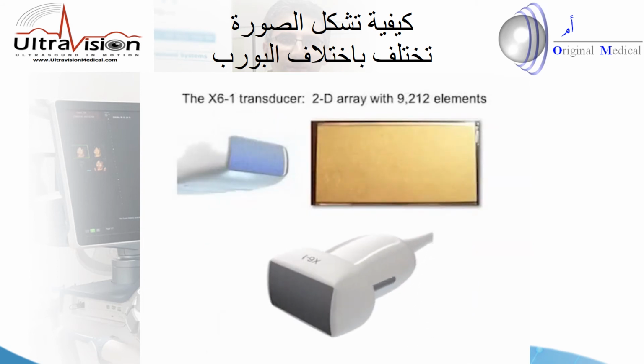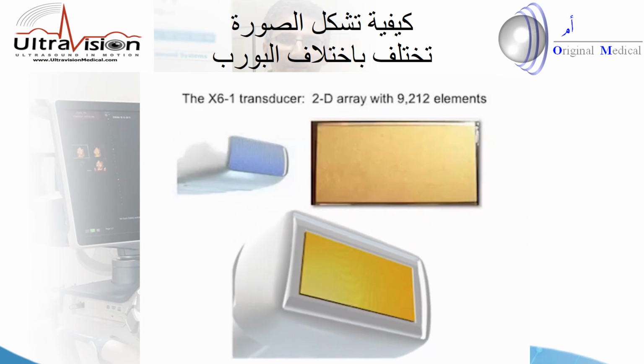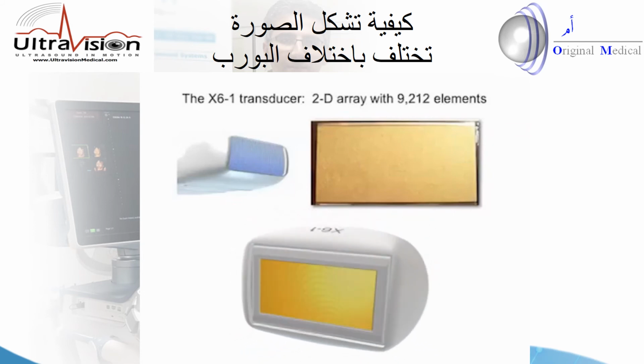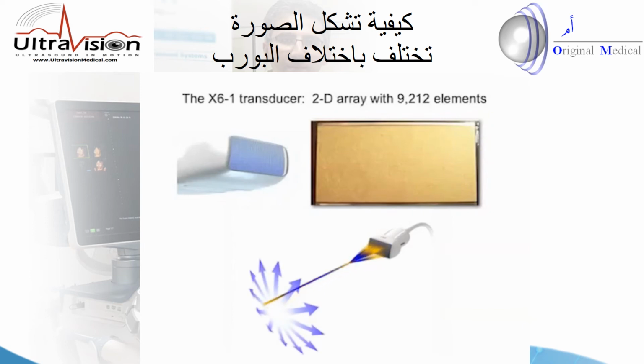The X61 is quite different. It doesn't have a line of elements, it has a two-dimensional array of elements. Although the area of the footprint of the transducer is comparable to that of a conventional abdominal transducer, there are a great deal more elements there, not 100 or 200, but 9,000 elements in the case of the X61. I think you can see immediately that such a transducer, if one had control of all of those elements, could be used in many different modes.